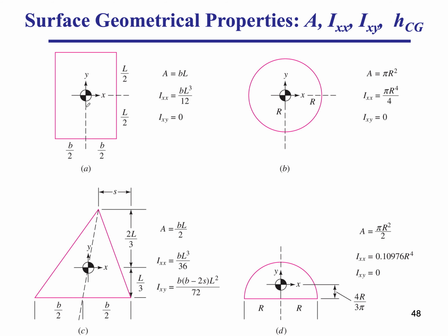So when you're solving problems, y was our main coordinate, which indicated the direction towards the free surface. So you want to keep, because there's B and there is L. B is along the X, and L is along the Y. So you cube the L, not the B. So it's BL cubed. That's going to make a big difference in your calculation if you make a mistake.